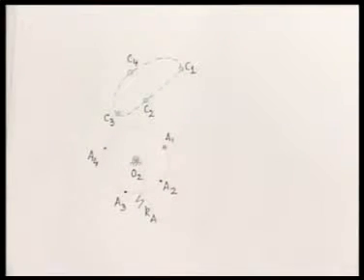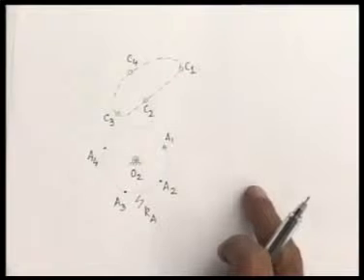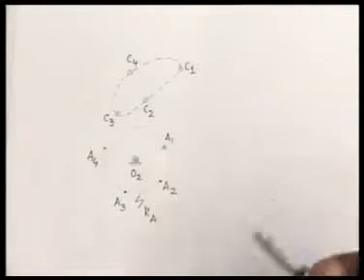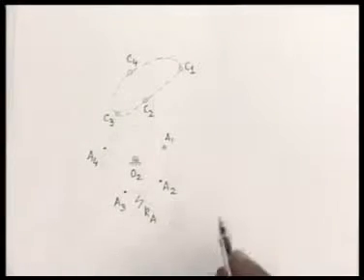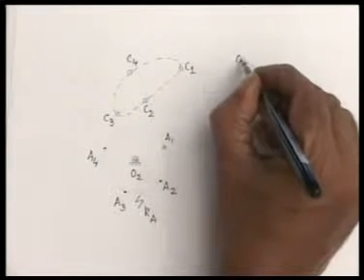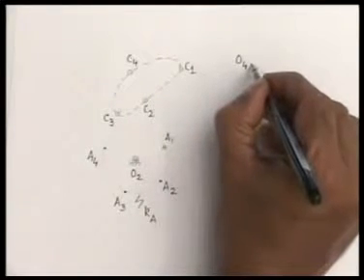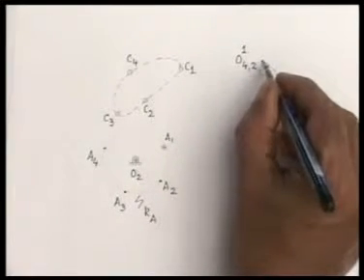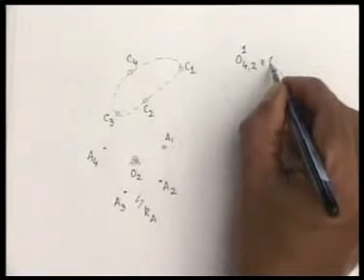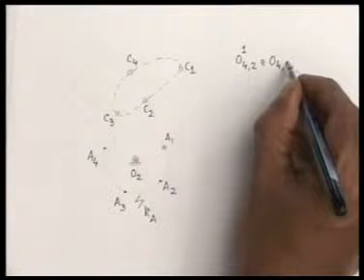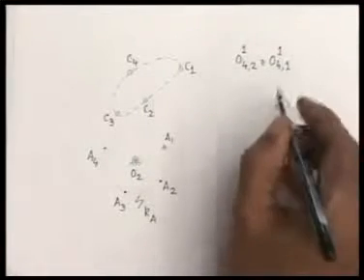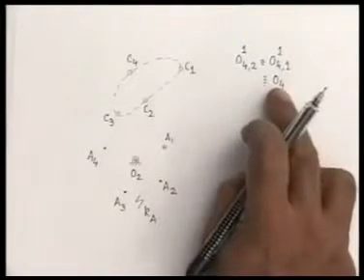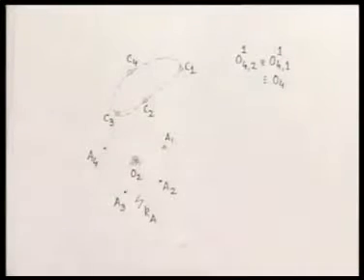As we know, we cannot choose O4, the other fixed hinge, arbitrarily. We have to choose it such that the 4 inverted positions of O4 become 3 distinct locations. Towards this end, we decide that O421, that is the second configuration inverted on the first configuration, becomes the same as O411, which is the same as O4. So we choose O4 such that these 2 inverted positions coincide.